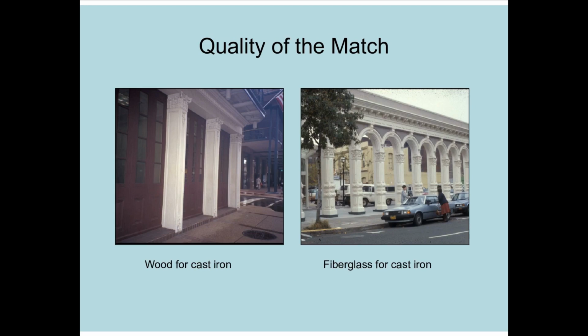While the goal may be to achieve an exact match when replacing historic material, most replacement involves some measure of change, if only minor. For example, new marble today will not be exactly the same as historic marble, even if it's from the same quarry. Thus, the evaluation of any replacement needs to take into account the quality of the match needed in terms of both appearance and performance for a given situation.